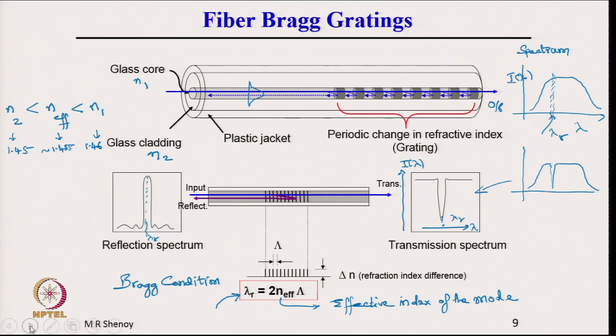All right. So, the mirrors are replaced by Bragg gratings of appropriate period. The reflection is required at the lasing wavelength. So, the period has to be chosen, the grating has to be fabricated with a period. So, lambda is the period, a periodic refractive index change in the medium.